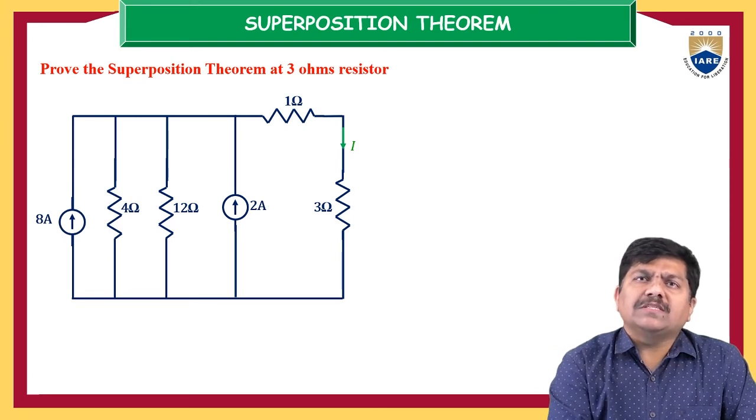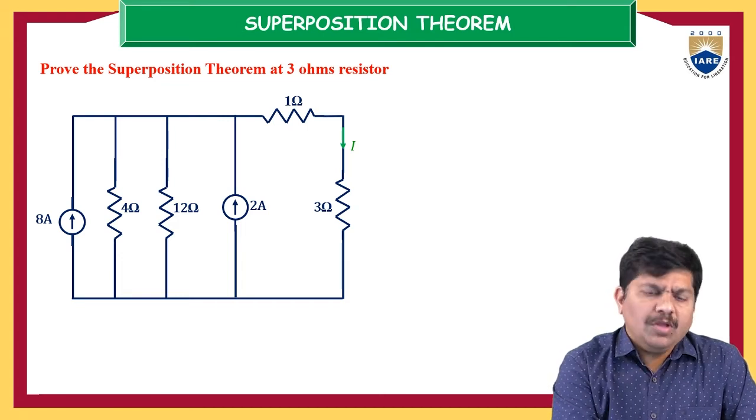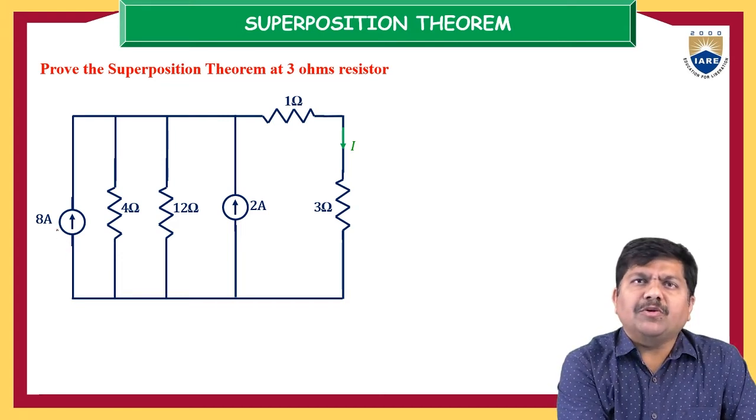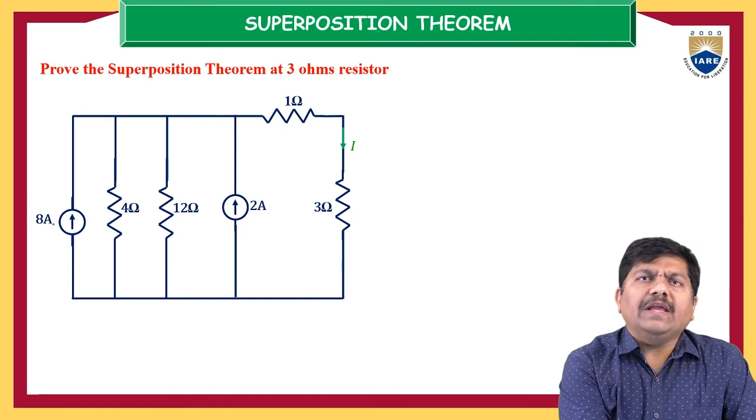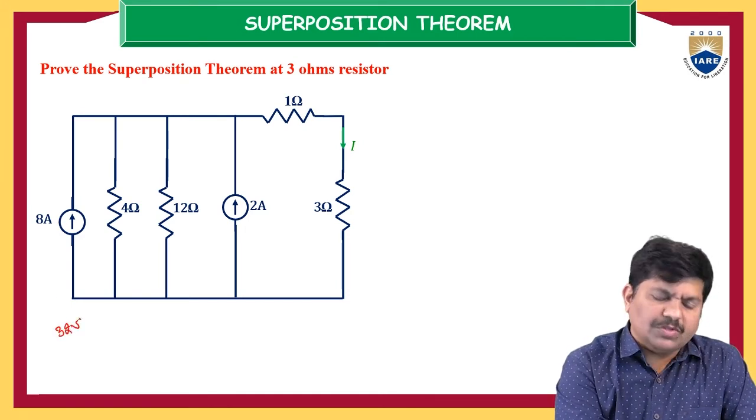Inside that box, one voltage source with one series resistor of 4 ohm can be converted into one current source having a magnitude of 8 amps with a source resistance. So how did we get this 8 amps? Because there is a 32 volts voltage source.